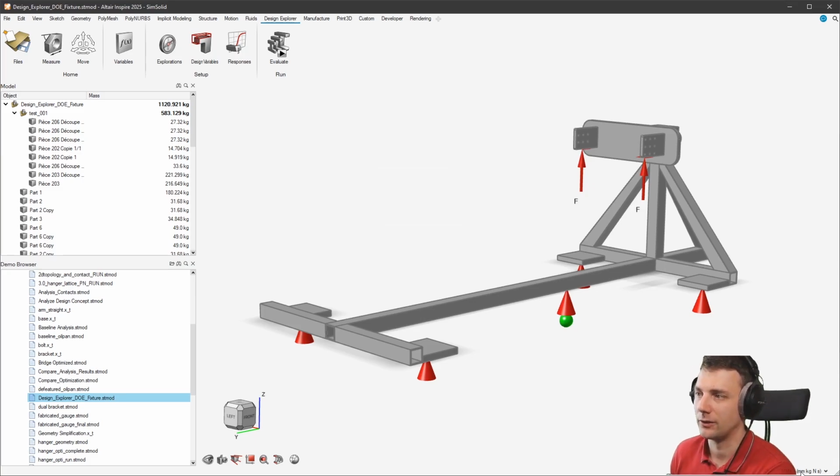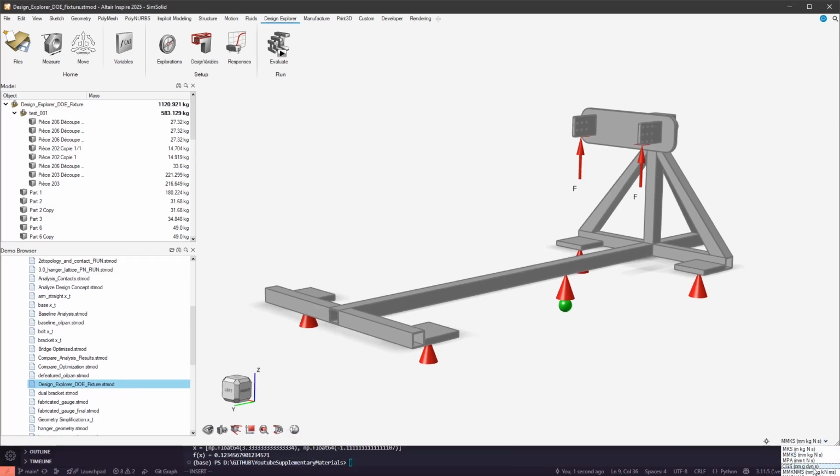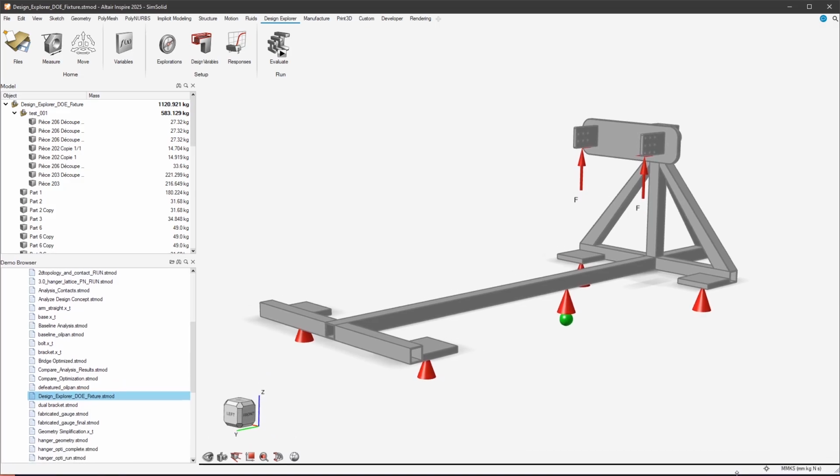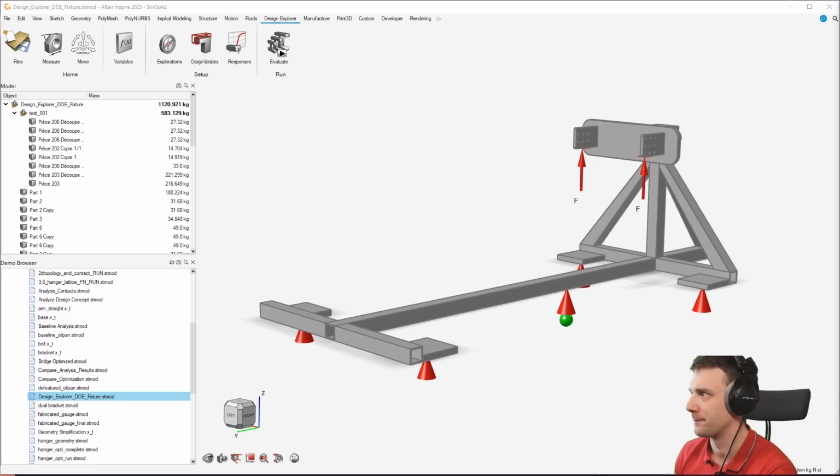Then another thing to check also is the unit system. Oh, I'm in the way, right? So the unit system down here can be set to whatever. Let me just quickly go up so you can see that here. Typically I'm going with the MPa, but the tutorial says that you should use kilogram, Newton and seconds. So this is just a hint on how the solver should interpret the things here. And it's good to set those, so that you know what you're doing, that it is a consistent unit system and that you're aware of it. So basically that's being set.